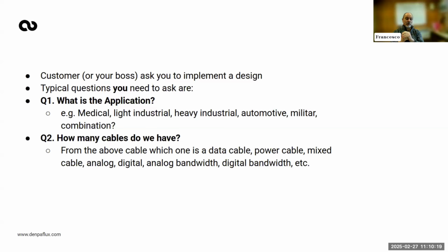Just to make an example, if you're designing something that controls the light of a building, and your control line goes in parallel to the main line, there are some quite severe tests you have to do on this cable, because usually this cable is longer than 10 meters. Yes, you need to do some tests like surge, and that could be demanding.